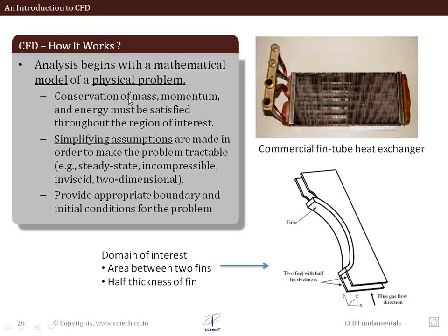Of course, it's not just the flow of fluid and the momentum equations that we need to solve, but also the energy equations. We try to simplify the problem, which is what we have done, by reducing the extent of the problem. We ask ourselves whether we can do a steady state analysis or whether we need to perform a real unsteady simulation, whether the flow is compressible or incompressible.